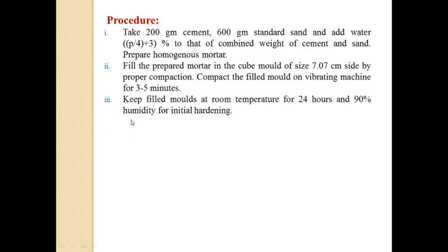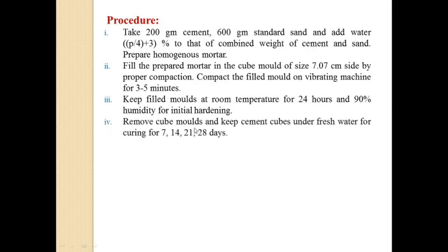Next, keep these filled molds at room temperature for 24 hours and 90% humidity for initial hardening. After that, remove the cube mold and keep the cement cubes under fresh water for curing for 7 days or 14 days or 21 days or 28 days.